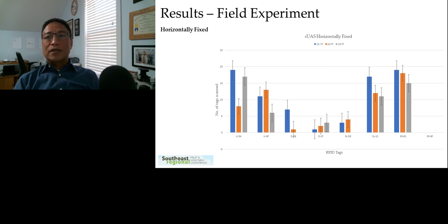This figure summarizes results for the number of tags scanned while the reader is in a static position based on distance and orientation. Tag 81 at horizontal 90 degrees sideways orientation shows the highest scan rate, followed by tag 5A at upward position. Then tag 12 at horizontal 90 degrees sideways left. In addition, tag 6F at horizontal 90 degrees sideways left has 0 readings.